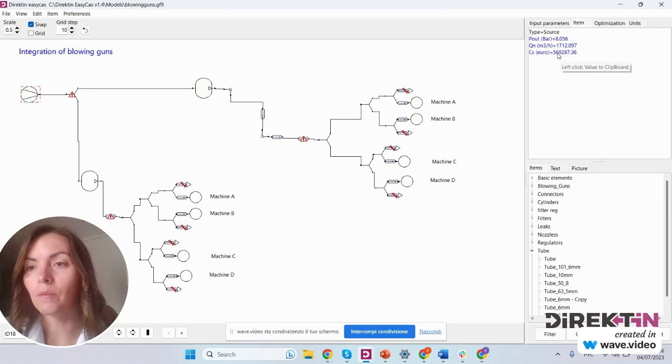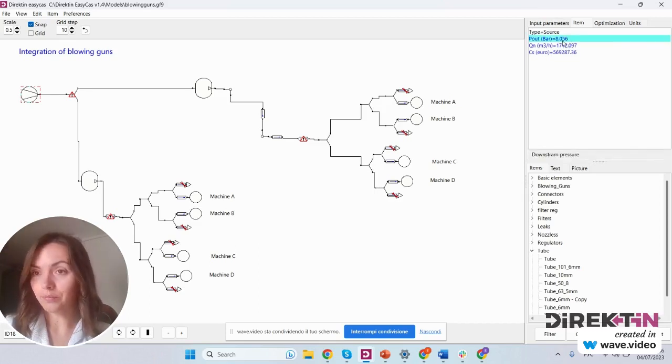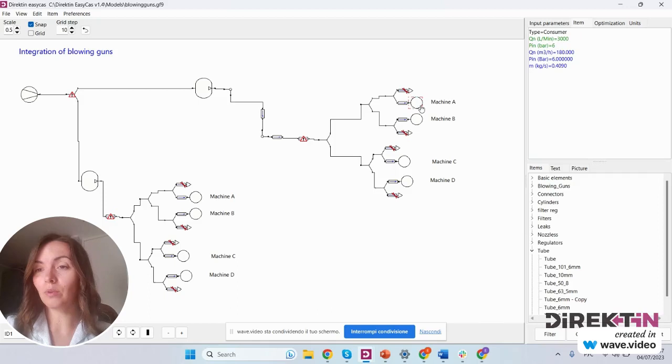It's about 500,000. We see the required cubic meters per hour, the required consumption for the compressor, as well as the pressure. We need 8 bar at the beginning of our system to supply those machines with 6 bar. Okay, so let's keep it in mind. It's 569,000 euros operational or energy cost for this compressed air system.